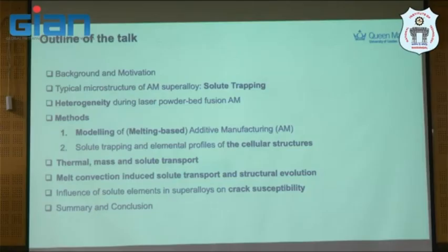I think, please bear with me if you're not in the metallurgy field. I'm trying to go as slowly as possible, because we believe this actually influences the solute segregation in superalloy, an important factor for crack susceptibility. So I will try to link this based on the analysis that we have done, and try to make some comments about how we can better design new superalloys with better crack susceptibility avoidance. And then summary and conclusion of the work.